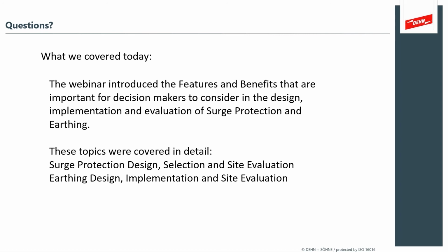Yes, as you mentioned, severed earth connections can lead to instrumentation problems. What kind of problems are we talking about? Well, the severed earth connection basically means that you're going to have unequal potential. So if there's a ground potential rise, the instrument will experience a different potential than the controller.